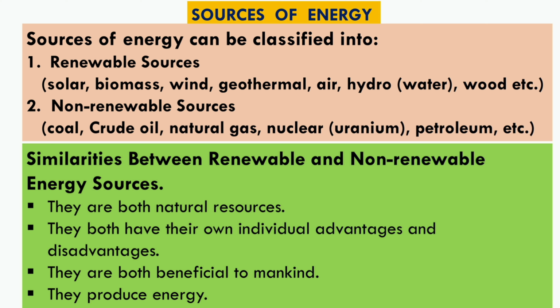This method is most inefficient, with overall efficiency as low as 20 to 25%. Due to availability of coal in huge quantity, the cost per unit generated is not so high. The disadvantage of this source of energy for generation of electrical power is that it requires a larger space for storing the coal and involves heavy cost of transportation where the coal mines are away from the generating station.